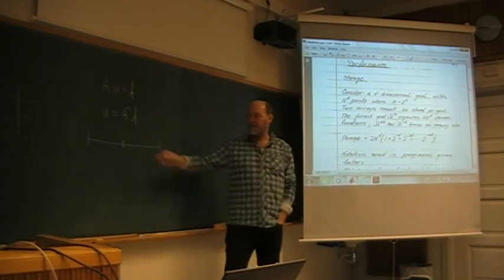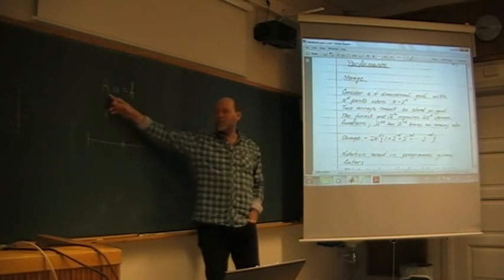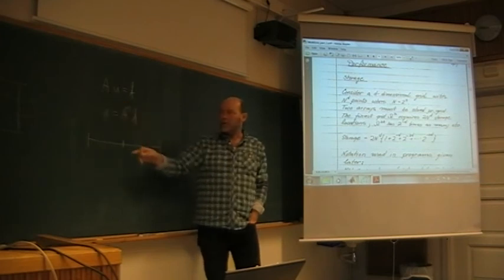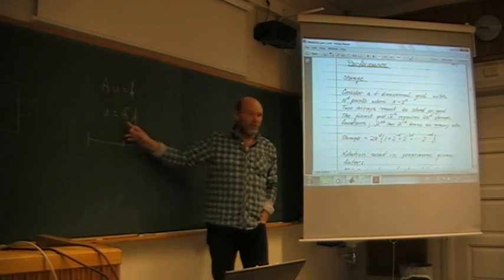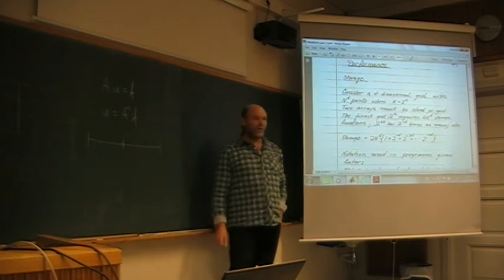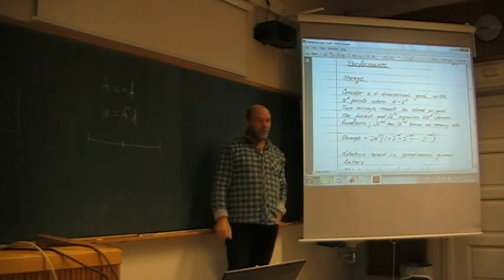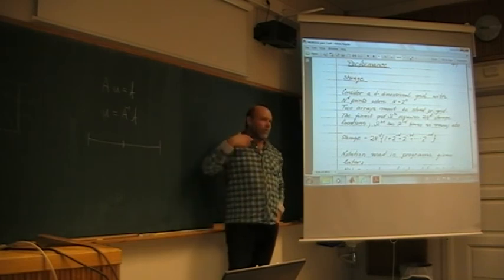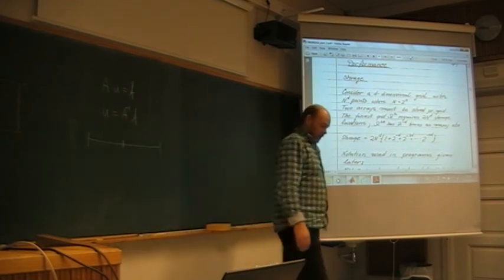Then you're in trouble. The inverse matrix is going to be full. Even though this one only occupies, say, a percent or something of all the positions, the inverse is going to be full. So with the direct method, you blow the memory of your computer very fast indeed. So direct methods are not possible for big problems. You don't have enough computer memory. Especially in three-dimensional problems, forget it. You can't use direct methods.